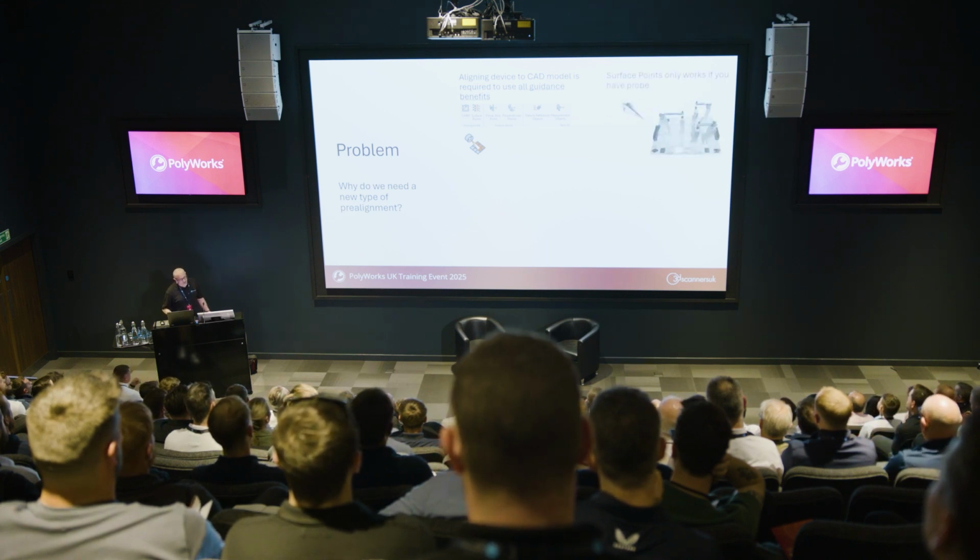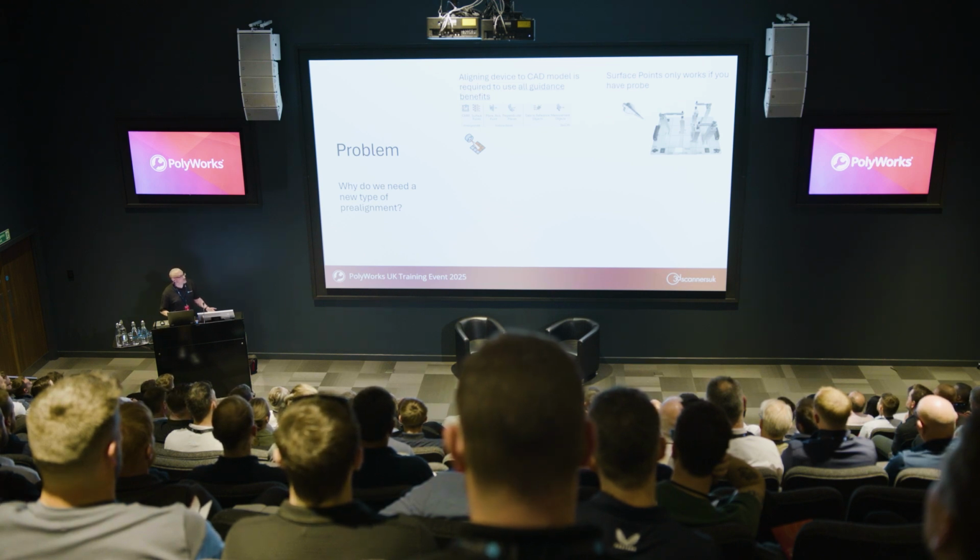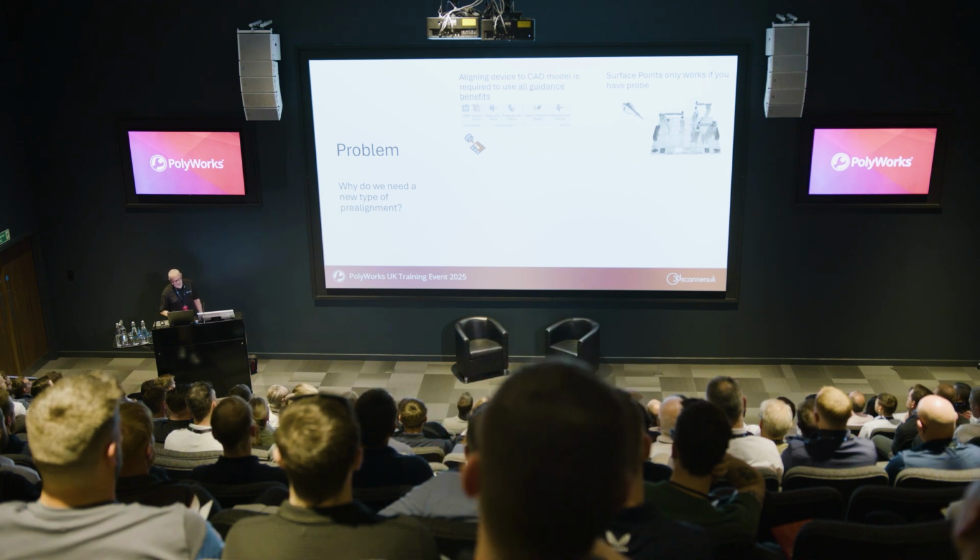If we're using surface point probing, that only works if you've got a probe available, and in a lot of cases you're going to need a special fixture to do that, to maybe clamp the part down to be able to do that initial alignment.